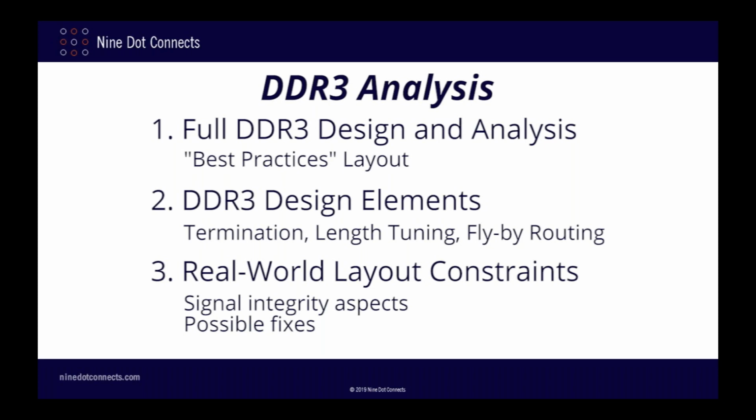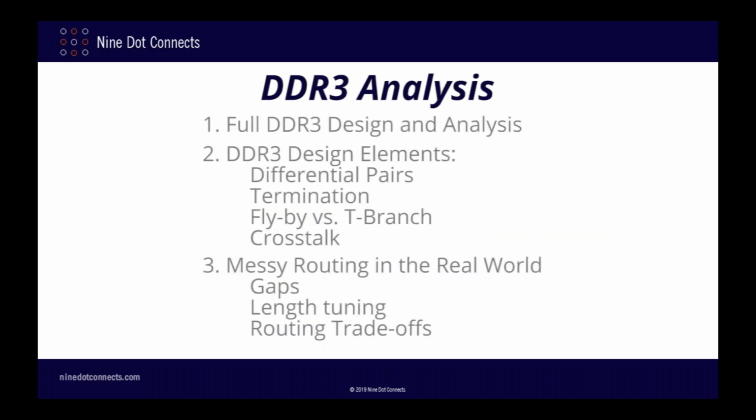I'll explore the signal integrity effects of these trade-offs and hopefully offer some guidance in your decision-making. Before I get started, here's a summary of what I'll be presenting today. First, I'll start off with a full DDR3 design and analysis. Then I'll move into looking at some of the elements within those designs, such as differential pairs, termination, flyby versus T-branch, and crosstalk. And as I said, I'll explore some of the ways the real world messes up our perfect designs and layouts, such as gaps in our paths, length tuning, and so forth.